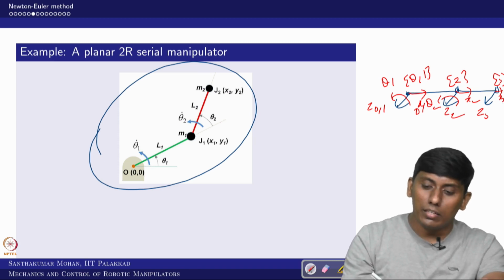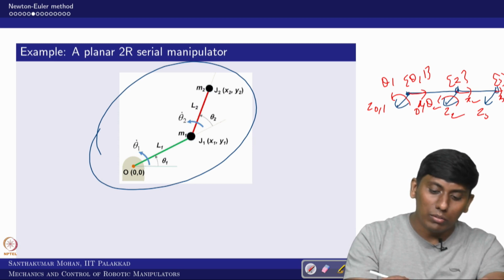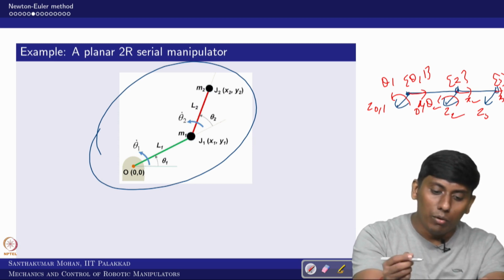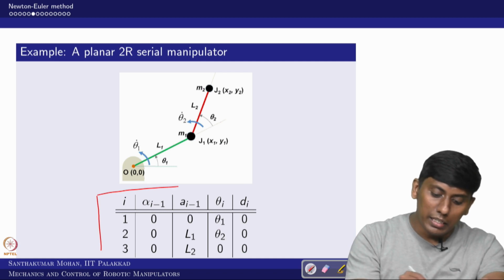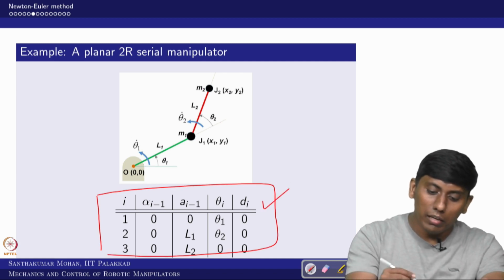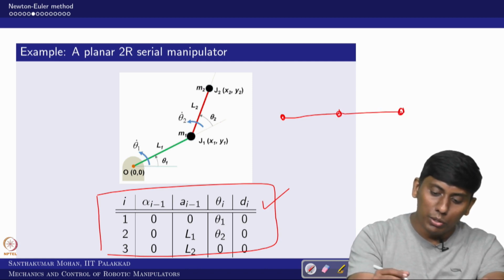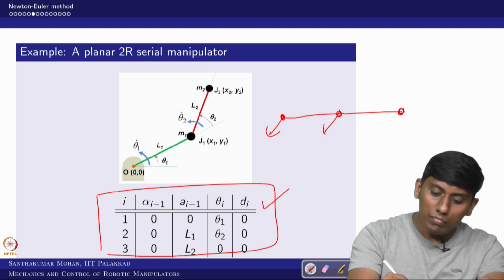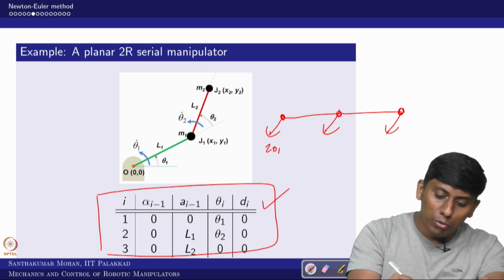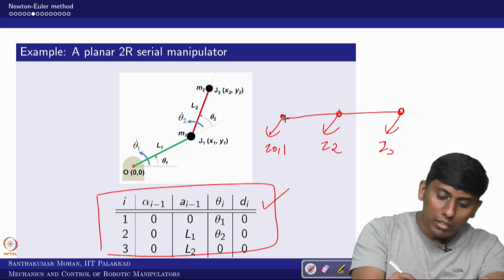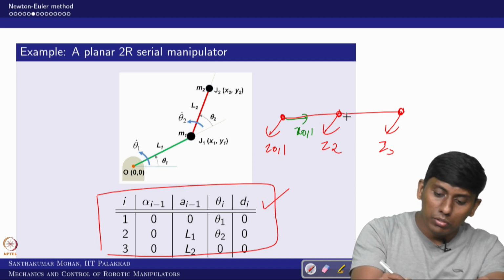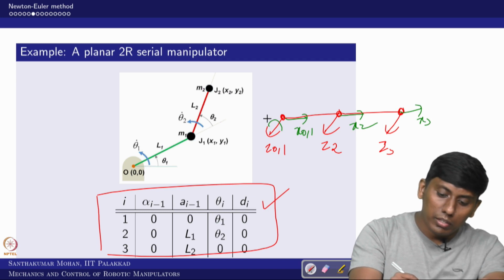So in the sense, you can find the DH parameters. I'll show it here for your purpose, because last time what I drew has gone out. This is Z0 and Z1 and this is Z2, this is Z3. I am showing how x0 and x1 go, this is x2 and this is x3. Now this is theta 1 and this is theta 2.